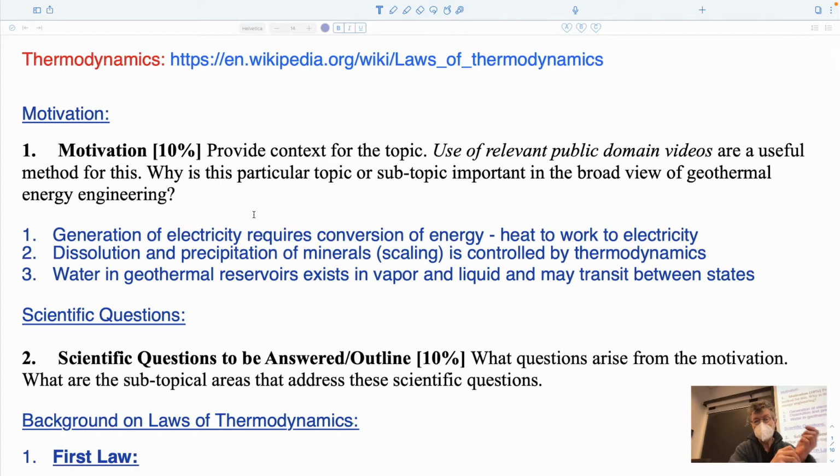And usually, to recover the heat from it, the highest energy yield is if it's a phase change, because we can use that phase change to drive conventional turbines. So we want it to be 100 degrees centigrade plus if desired, but we can also do it by transferring heat from the water to a second fluid in a closed system, a binary system, that boils at, say, 40 degrees centigrade, in which case we can do the same thing.